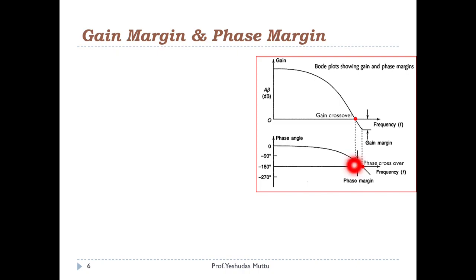Okay. And the gain margin is the difference from 0 dB to that point, which we have found due to the phase crossover frequency. Okay. So if I find the gain margin, this point is negative, right? See, it is below 0, so it is negative. So it is 0 minus of minus this particular value. Let us consider minus 20. So 0 minus of minus 20 is 20 dB. So the gain margin is positive, which is 20 dB. Fine.